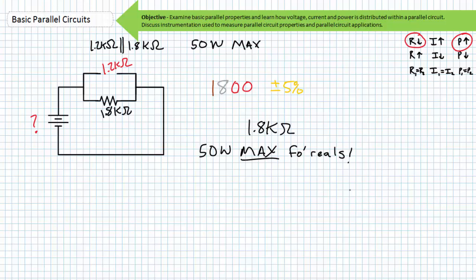Given our understanding of this resistor's unwillingness to exceed 50 watts, it sounds like the missing 1.2 kiloohm resistor may have been dissipating 50 watts at the time of its sudden disappearance. Use your understanding of the numerous permutations of the power formula to determine the voltage across this 1.2 kiloohm resistor dissipating 50 watts, as well as the current through it. Dividing by R both sides and taking the square root of both sides, we are left with current equals the square root of power divided by resistance.